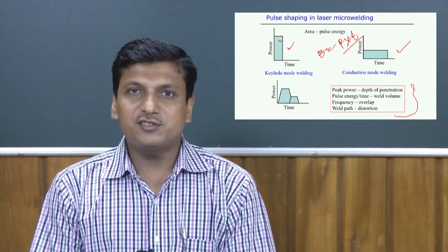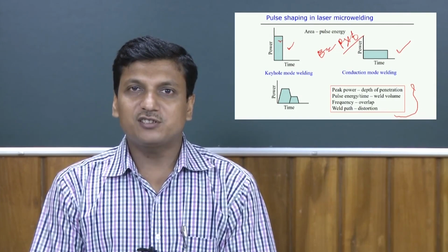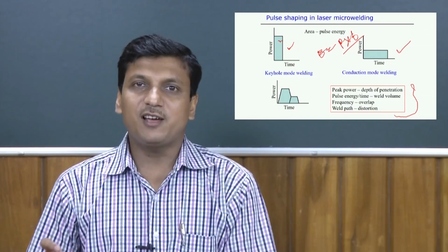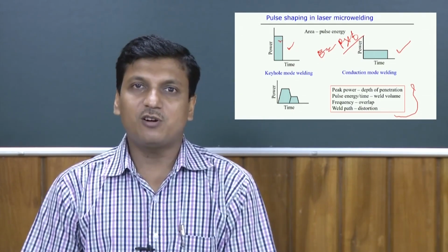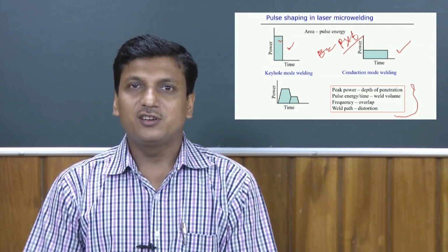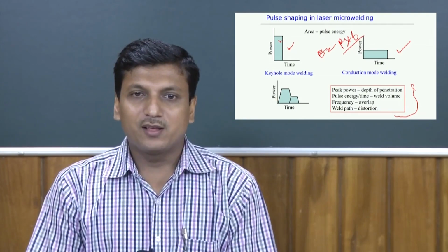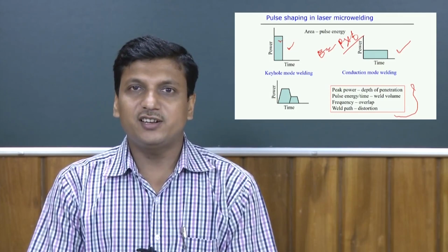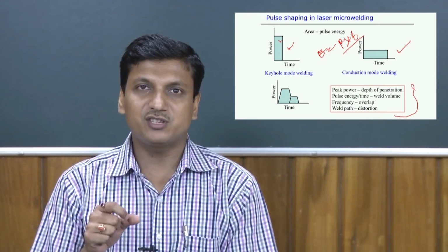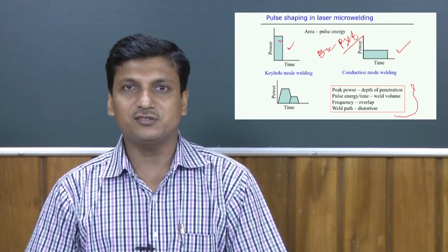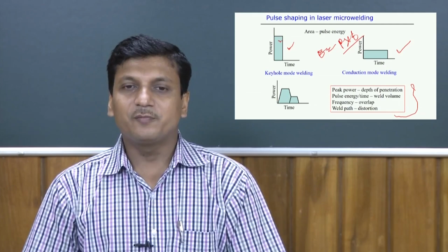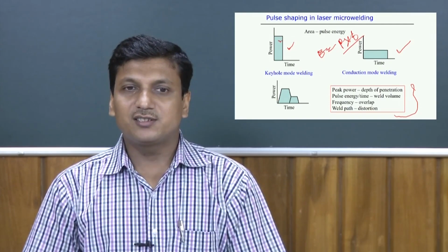And then the frequency of the application of the laser energy actually creates the overlap, or overlapping spot, in the sense. So, that frequency controls the overlapping of the energy on the substrate material. And the weld path, in general, since the laser weld is confined to a very small area as compared to the arc welding processes, may be more related to the distortion level of the sample.